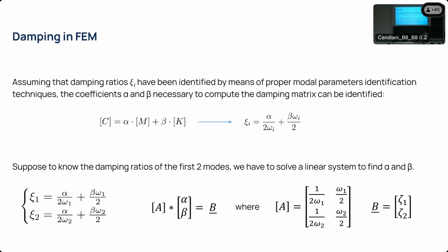And the nice approach about that is that if we are able to diagonalize the mass and the stiffness matrices, we are able to do so with a linear combination, which is wise, because then we can use the modal approach, we can reduce the number of unknowns, the degrees of freedom of a structure, and then we are able to solve it numerically much faster than if we have a non-diagonal matrix.